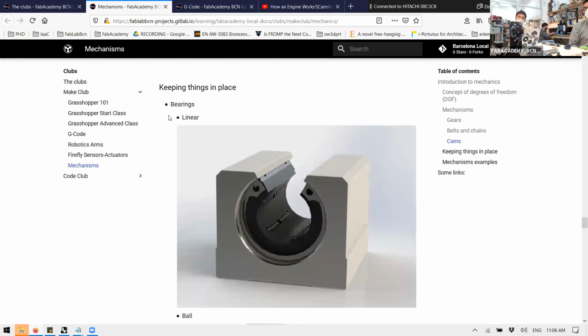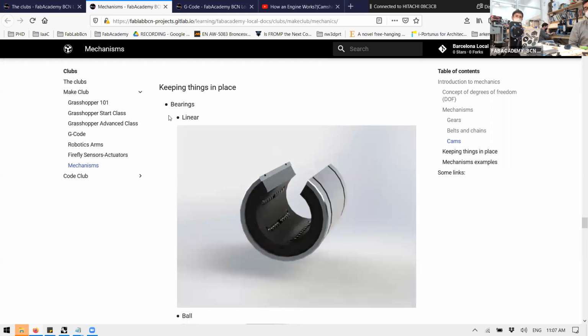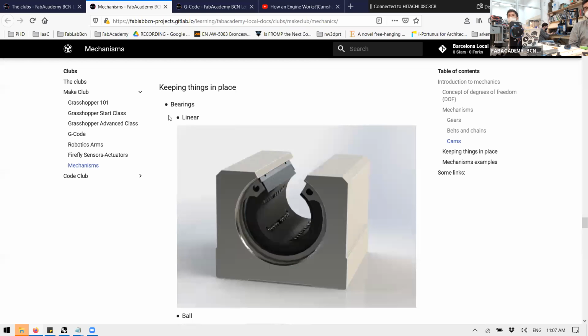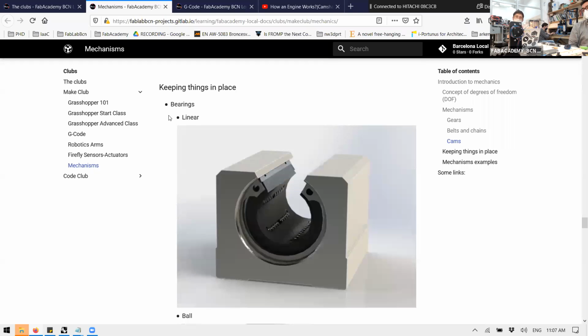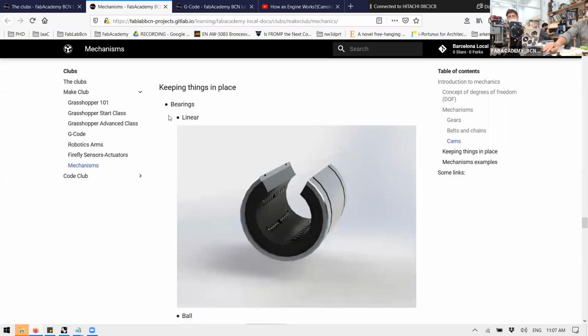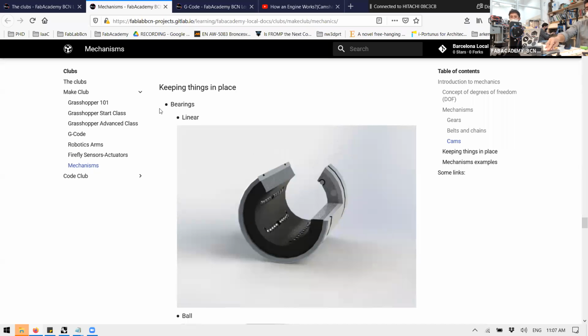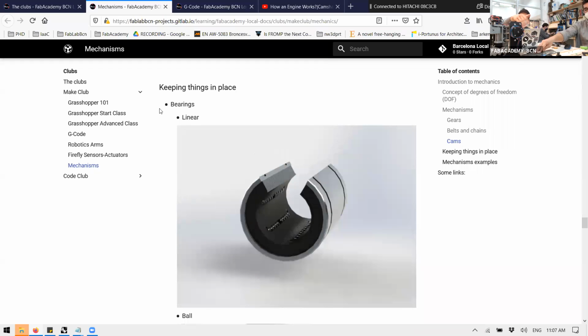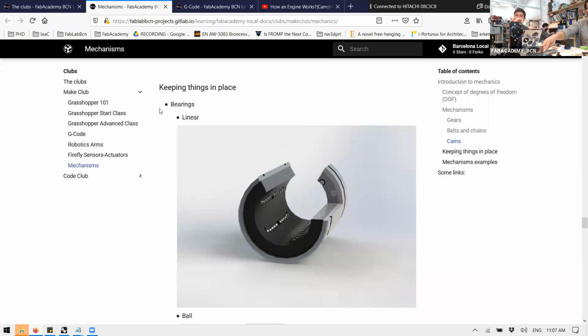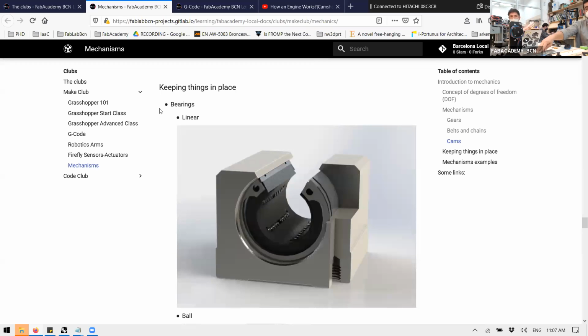You take the motor and the power supply, and for whatever amount of movement you are trying to achieve, you see how much current you're drawing. If it's over the specs of your motor or your drivers, or you never achieve the actual movement you want because your electronics are limited in terms of the current they can supply, then you either need to reduce the friction, or if you cannot, you have to increase the size of the motor.